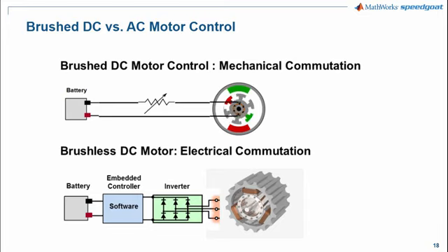In our case today, the feedback comes from a position sensor attached to the motor, and that feedback will be used by an inner loop to control current at 10 kHz and an outer loop to control motor speed at 200 Hz. I might point out that we have a version of this control running on a performance target machine at 50 kHz.